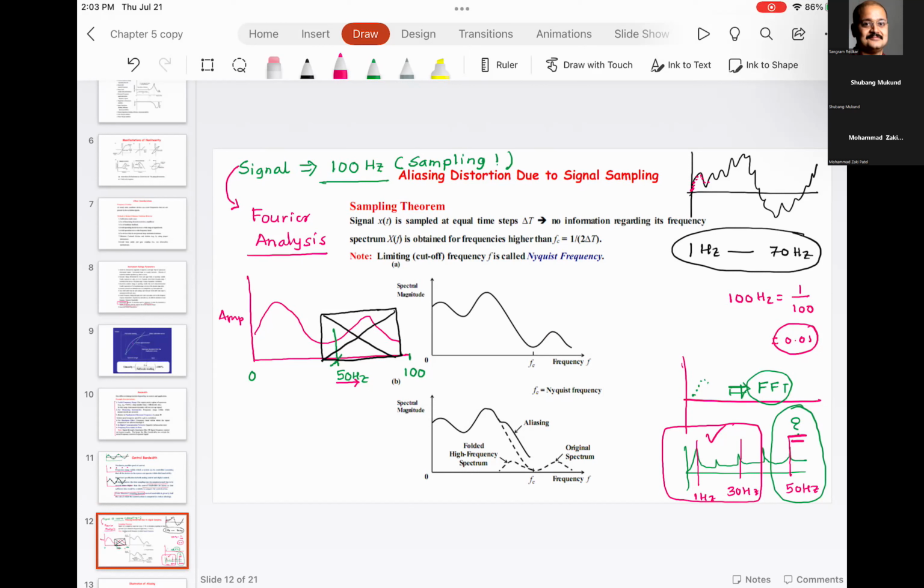Please understand, all these parts vibrate or rotate at different frequencies. How do you pinpoint which part is bad when you have this integrated system? The classic way to do it is, put an accelerometer on that shaker table, get the vibration signature, do the FFT, and see which is the most dominant frequency.